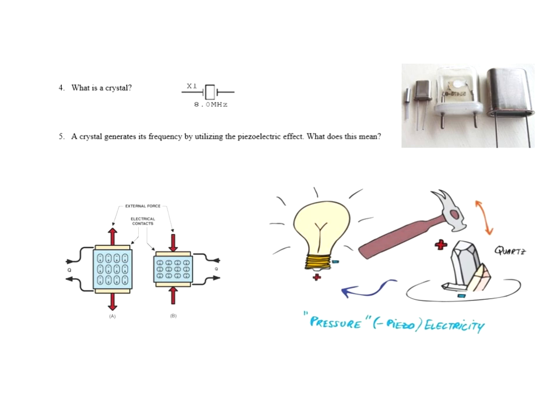Another kind of oscillator is a crystal oscillator. Crystal oscillator uses a quartz crystal. Here is the schematic diagram of a crystal, a quartz crystal. A block of quartz separated by two plates. Looks kind of similar to a cap, but it's not. What is a crystal? A crystal is a piece of quartz that behaves like an LC circuit. It'll generate a certain frequency. The frequency that it generates will be determined by the size and the cut of the crystal. Generally, the larger the crystal, the lower the frequency.